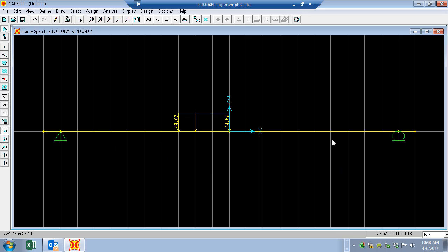So the same idea, what would we do over here on this element? Well, we want the load to go from 0 to 3, right? So if I come over here and look at the second element, again, it's 10 inches long. I want the load over the first 3. So this would be our first point. At 0, we want to have minus 40. At 3, we want to have minus 40. And then at 3, we want to go to 0. And then at 10, we want to go to 0. So see if you can figure out those coordinates and enter them back into here.